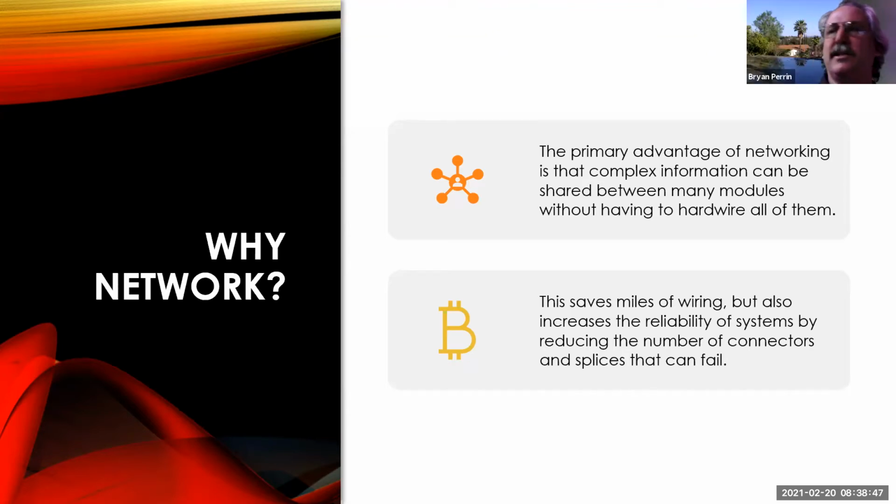So like I said, some areas we have redundancy, some don't. And when we look at network structure, we'll see some networks have really good redundancy. Other networks are, you're done. But that's also why we have more than one network on the car. Because a modern Porsche might have 168 modules. We don't put 168 modules on one network because if that network went down, if it was shorted, no one could talk, no one could do anything. So we break it down into smaller module areas.